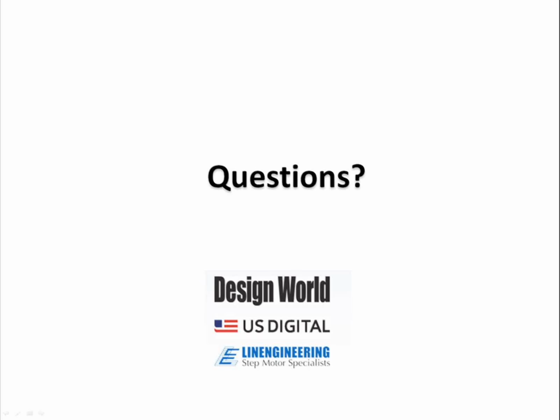All right, and along with those environmental questions, there's a question that came in on what do you recommend for encoders in a radiation environment? It's optical. The note here: optical doesn't work after time due to the clouding of the optics. Yeah, that's a tough environment. Indeed, the optical ones will have issues, plain and simple. It's just a function of time, as you mentioned. So you have to start looking at other technologies. You have to start looking at magnetics, maybe resolver at that point. So other technologies have to come into play.